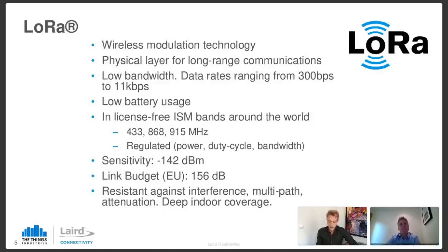And the reason why you get such a long range is because of the link budget. The link budget is really high. The theoretical range of LoRa is, I think, around 850 kilometers, and there have been some field tests with weather balloons going beyond that, with 5 milliwatts of power. So that's really what you get theoretically with LoRa. It's a really great modulation for low power transmission of data.